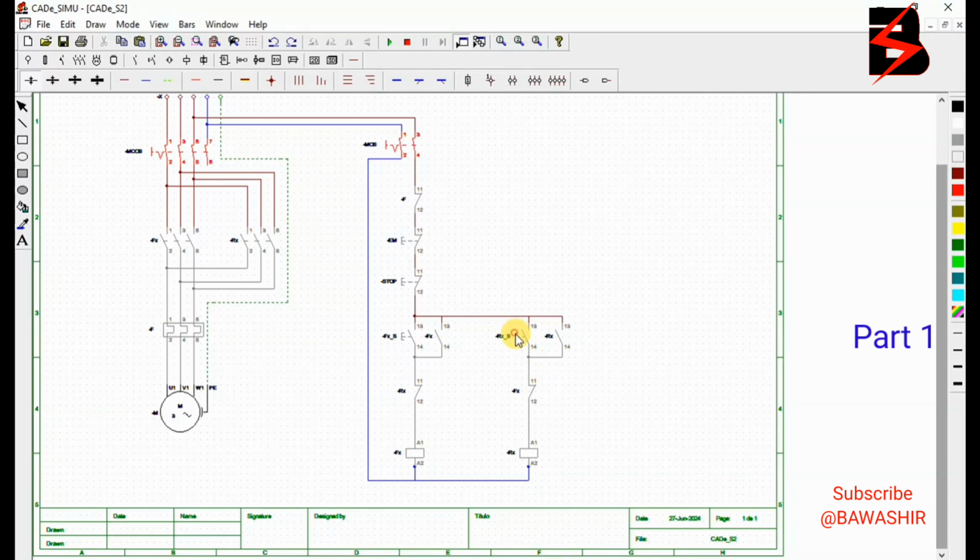So now when you switch on anti-clockwise, you see our motor is now running in the anti-clockwise direction. The same way, this coil here opens its contact which is on this line here. So however much you switch on the clockwise rotation, it does not go on until you press stop. So briefly, that is how we control the direction of rotation of a motor.